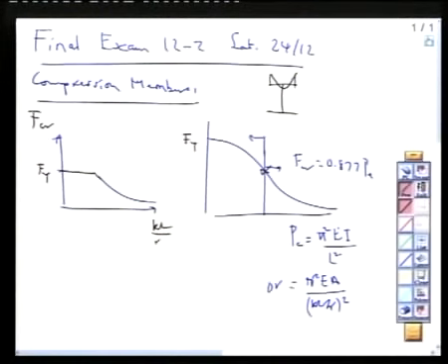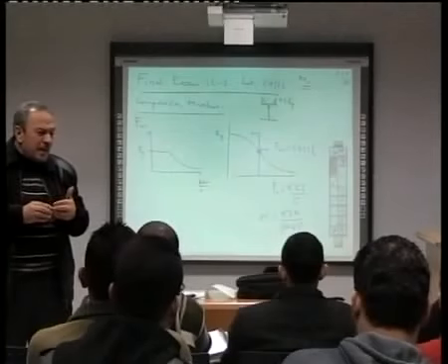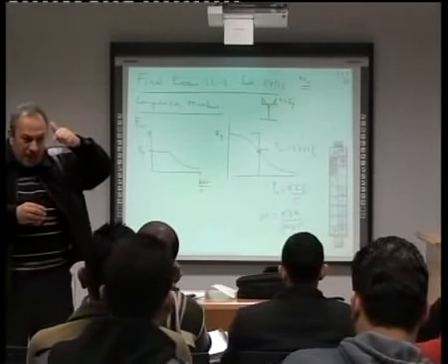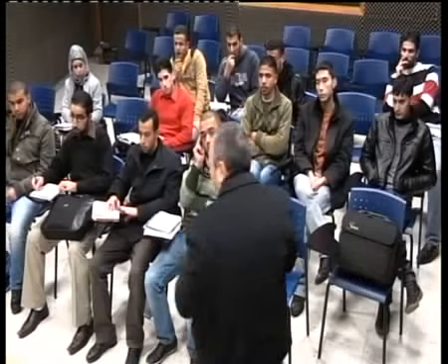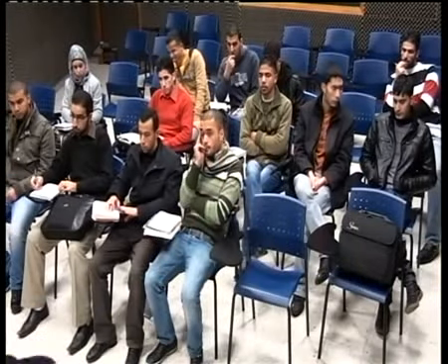To what value? You go to your exam next Saturday. What is MR? How do we calculate MR? 0.7. Why 0.7? Because we have 0.3 F yield, what? Residual. So the 0.3 F yield residual is one factor. The out of straightness, we never have a column that is what? Straight. We have what? Out of straightness. This does not affect bending capacity, but it affects when we have an axial load that will introduce an additional P delta effect. So we spoke about other items that affect this curve.